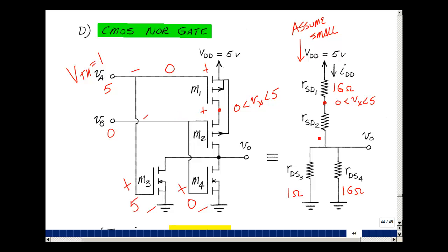We don't know the value of this resistor. It could be low, it could be high. I'm just going to label the fact that I don't know this value of resistance. How does that affect the calculations? Well, first of all, is the current small? The resistance seen by this battery is 1 gigaohm plus an unknown number plus another 1 ohm. It's at least a gigaohm in size, and so the current is small. We have something in nanoamps.